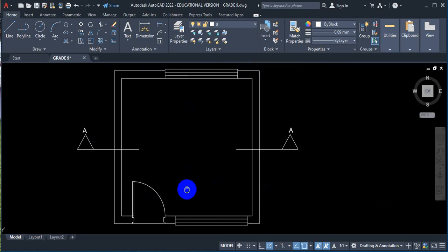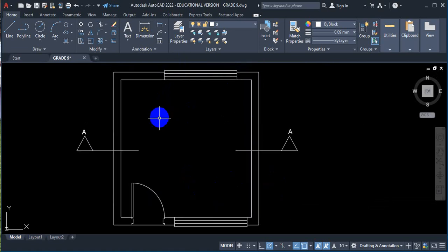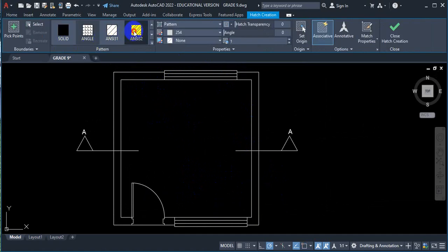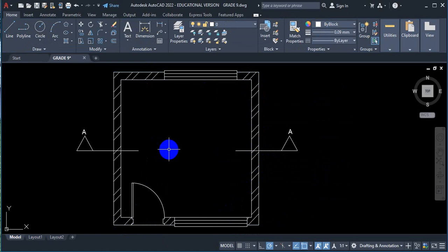So now that's complete. So it means we can now do the hatching. And the hatching must be a common brick type of hatching, where you hatch in at 45 degrees. Now your drawing is now complete except for placing in your labels. So now we're going to place the labels. This is known as a room. The floor finish here, we assume that it will be tiles.